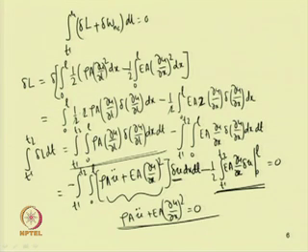You will have a minus term here, T1 to T2, 0 to L, rho A u double dot, E A del u by del x whole square, del u dx dt, minus half T1 to T2, E A del u by del x del u, 0 to L. So, this term will reduce to minus E A del u by del x whole square del u dx dt, minus half T1 to T2 E A del u by del x del u, 0 to L. In this way one can derive the equation of motion by using the extended Hamilton principle.